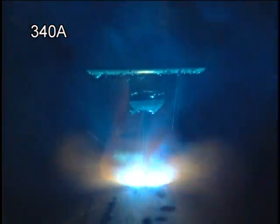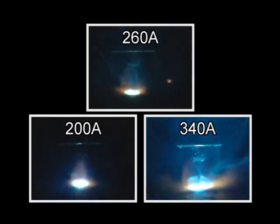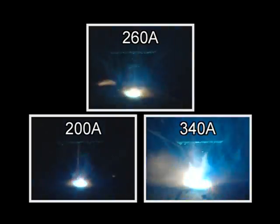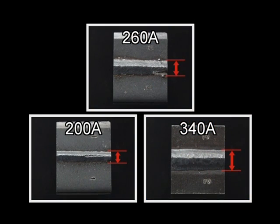As the amperage is increased, the amount of melted base metal is also increased due to the high melting rate of the welding wire, which results in high thermal energy. The weld pool size is changed when the amperage is increased, even when the travel speed is kept the same. The weld bead width becomes wider as the amperage is increased.